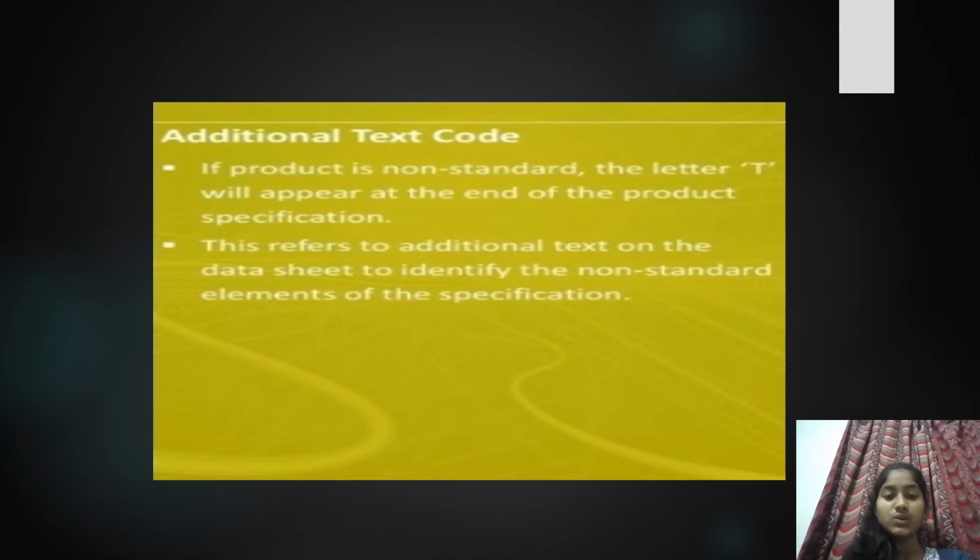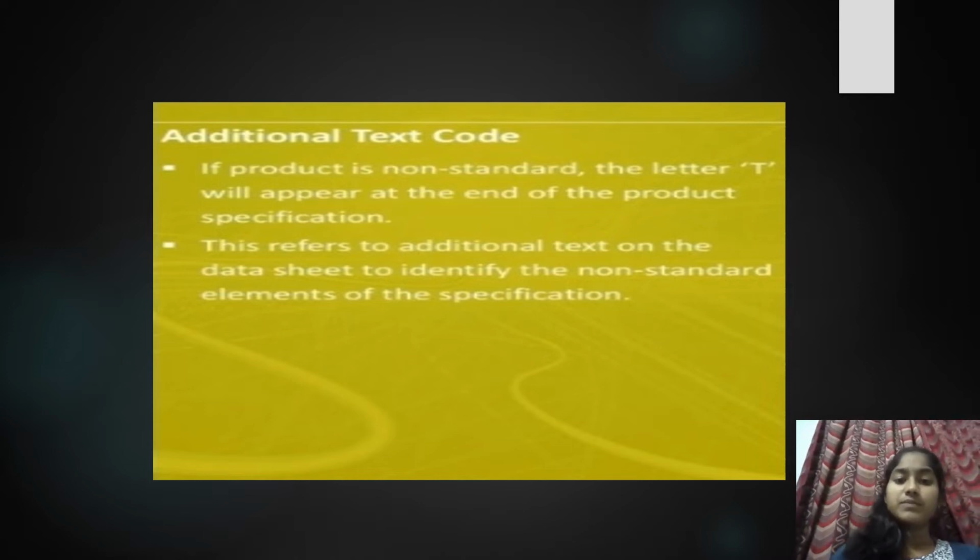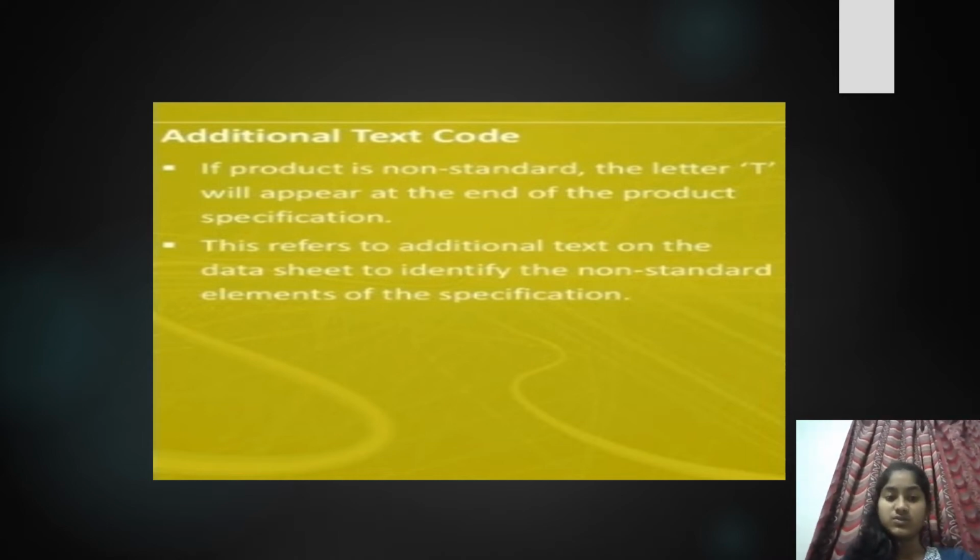In most VCXOs, a pair of back-to-back diodes are placed across the crystal. A reverse bias is applied to the anodes of the diodes, which then act as a variable capacitor across the crystal. In most cases, a Colpitts oscillator circuit is used.